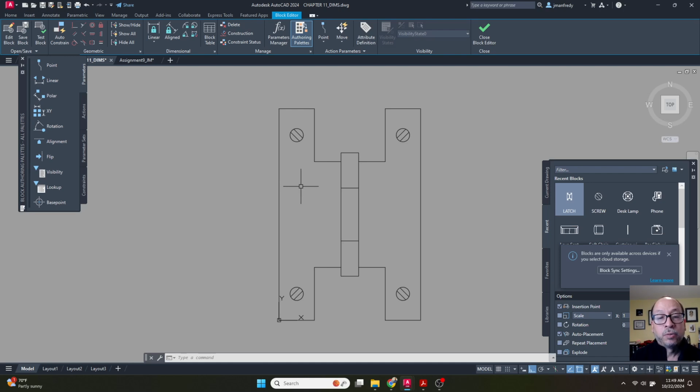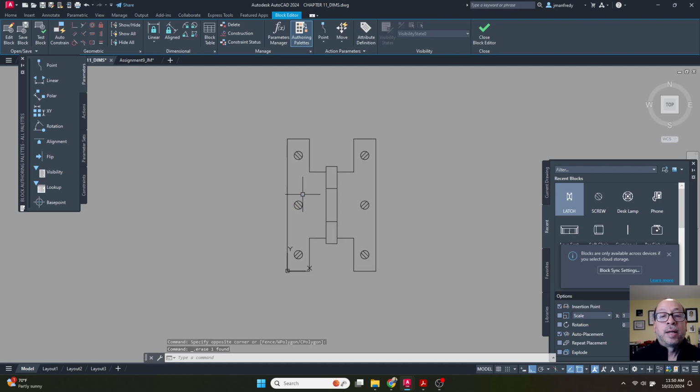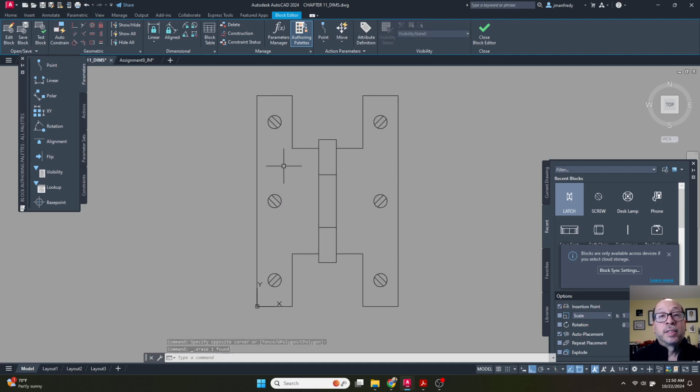And so I need to draw a line from the middle of this and then copy this and this from their center. Again, if you can't find the center, you type CEN, enter. There, it finds the center and nothing but the center. Make it perpendicular to that line. Escape, erase this guideline here. And what we're effectively doing is we're updating the block with this new redesign.